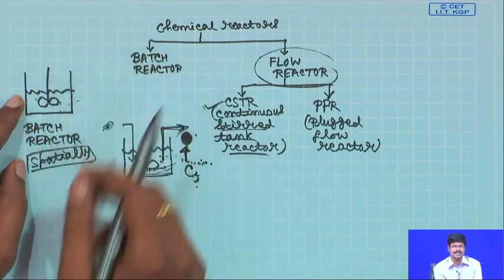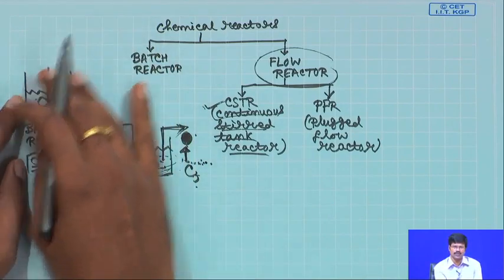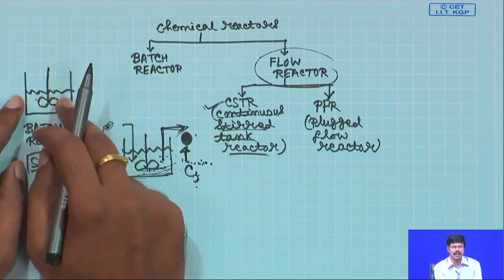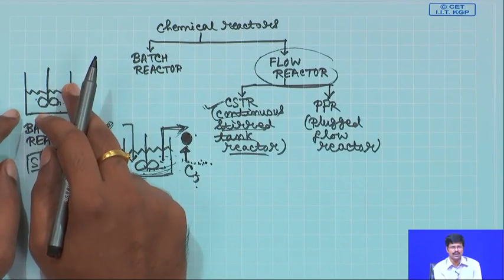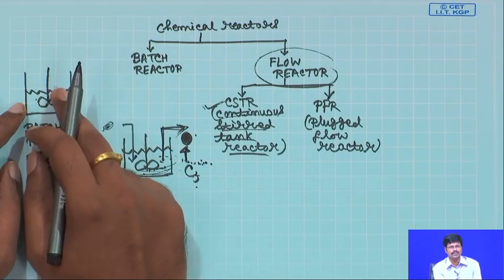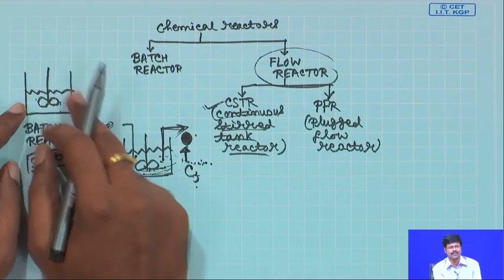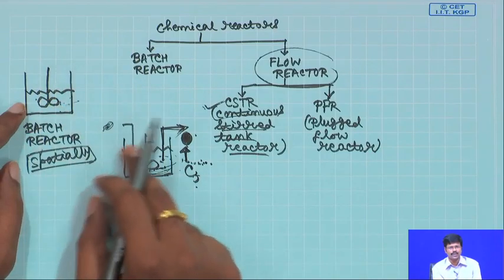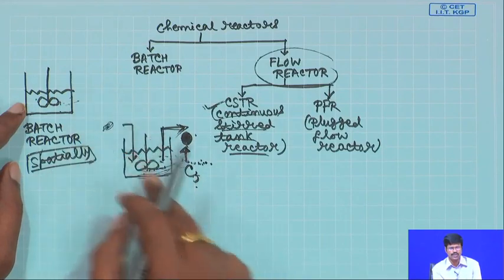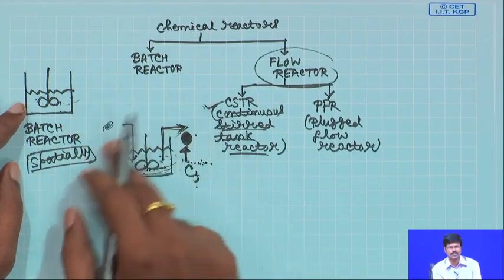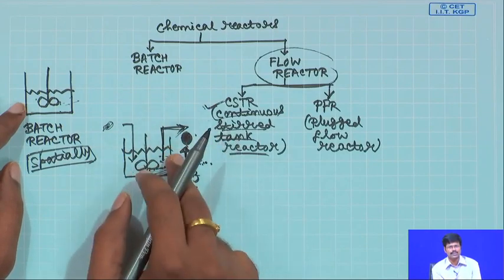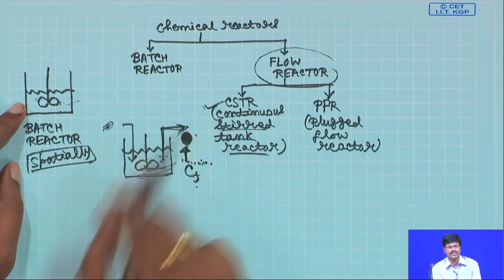So, batch to batch reaction: maybe one batch you put, the reaction is over, you put another batch. Typically the labor cost is higher, maybe the reactor cost is lower, but this is suitable for smaller scale reactions. But for big scale reactions the flow reactor is suitable, because something is going in, something is coming out, and you can continuously go on. This reactor may cost a lot, but the labor cost is much lower because this is an automated process.